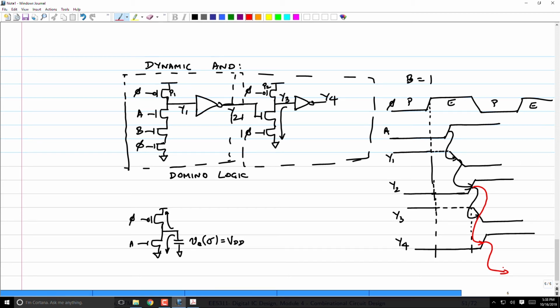Okay. Any questions here? Yeah. True. See, therefore, the moment I start making a circuit, then there is a spec that has to be met. It's not how many you have to put. You have to size these so that they meet a timing constraint. I can put any number as long as I can size it so that they can meet the timing constraint.